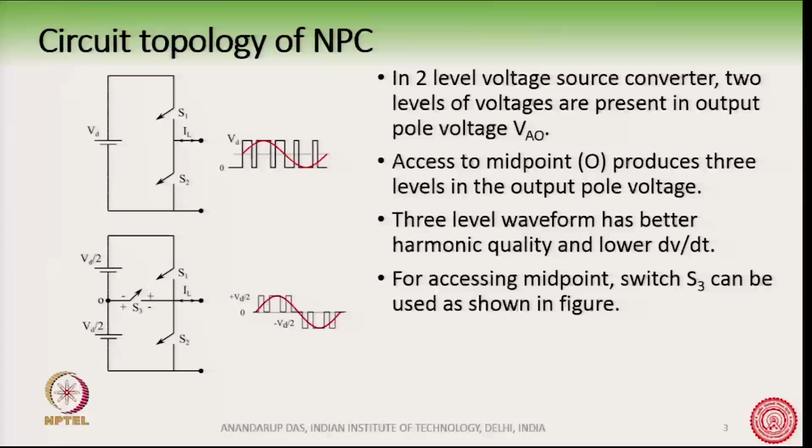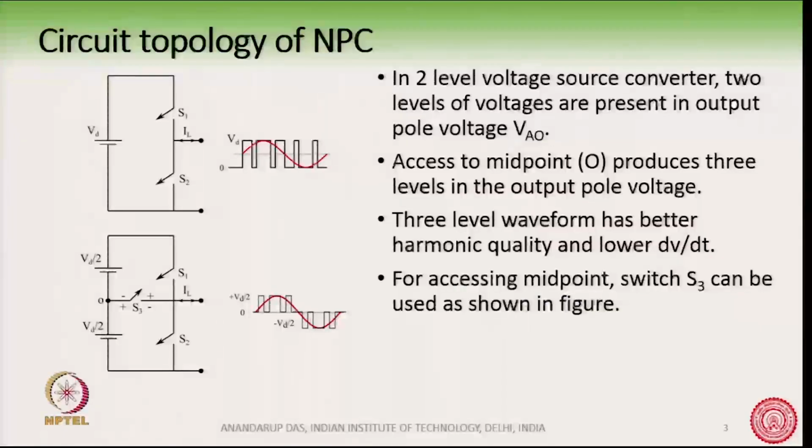there are several drawbacks which we have said earlier, and that is why some people go for a multi-level converter in its design. One drawback is that we need a high switching frequency of the switches, so that the size of the filter is reduced. If you do not have a filter, then sometimes dV/dt on the motor, for example if this converter is driving a motor, can be quite high, especially with a long cable.